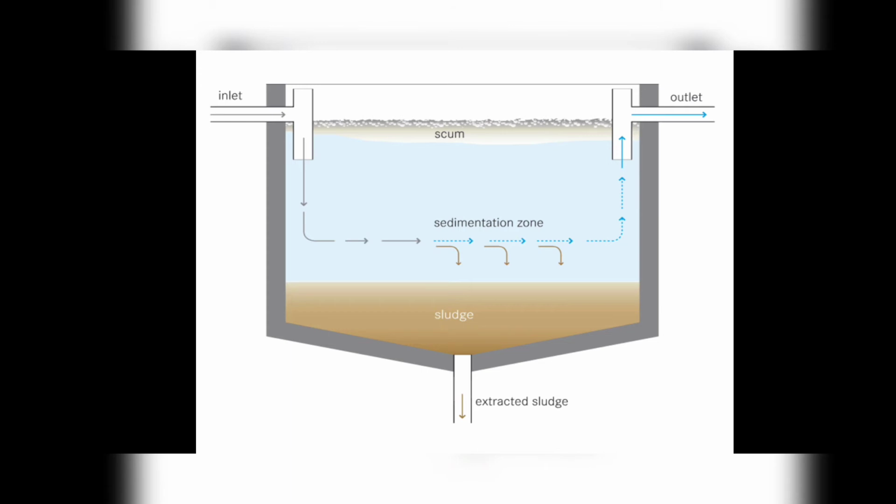Pumps are used to pull the settled sludge out of the clarifier and send it to a sedimentation or disposal pond. The water that passes over the weir is collected and transferred to the filters. The reason clarification occurs before filtration is so the majority of suspended particles can be removed prior to filtration, which avoids overloading the filters and thus allows much more water to be filtered before the filters must be backwashed.